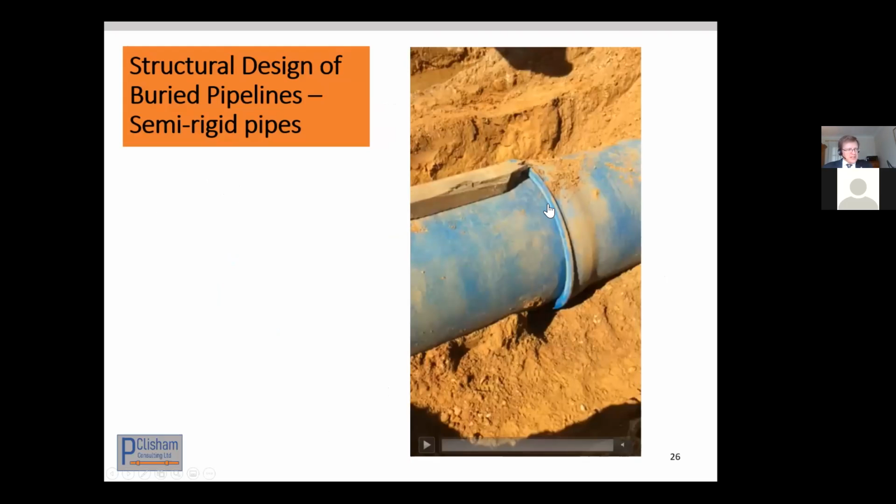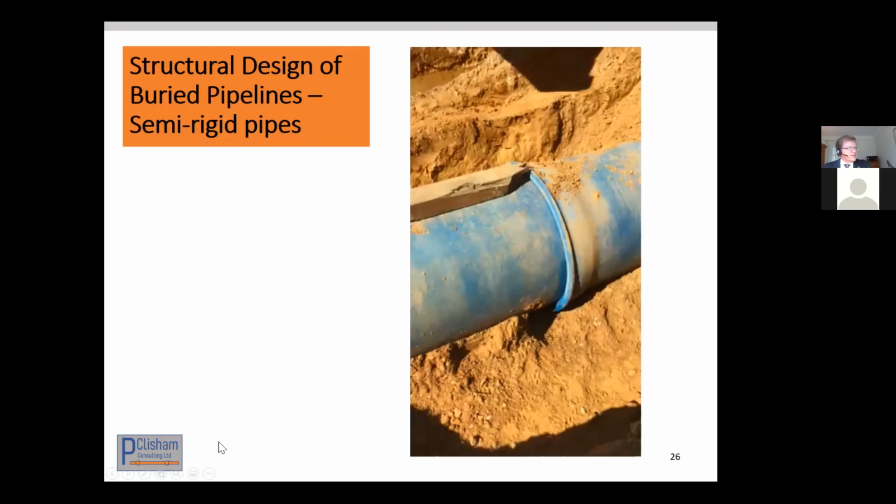So we have a ductile iron pipe here that's under pressure. This is 900 mil diameter, and the limit that the manufacturer says that you've got on the joints is a deflection of 3%. The joints can accommodate a 3% deflection. So that's the limiting factor.